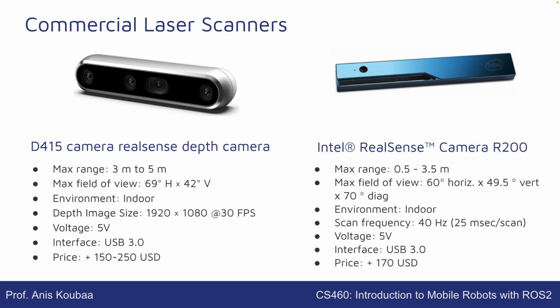So when you have an image, which is 2D, the laser scanner or the depth sensor inside can also give you how far a pixel in the image is. Okay, in this case, this is what we call the depth image. It's a 2D image, but it also gives you another dimension in the Z direction, which is the depth. And usually they give around 5 meters. They don't have a very large range. Okay, and this one is 3.5 meters. Field of view is also most of the time limited. It has horizontal and vertical, so like the 3D LiDAR, it's over the 2 dimensions, horizontal and vertical.